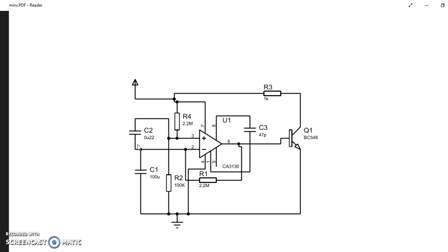An ordinary radio frequency detector using a tuned LC circuit is not suitable for detecting signals in the gigahertz frequency band used in mobile phones. The transmission frequency of a mobile phone ranges from 0.9 to 3 gigahertz with a wavelength of 3.3 to 10 centimeter. So a circuit detecting gigahertz signal is required for a mobile bug. Here the circuit uses a 0.22 microfarad capacitor to capture radio frequency signals from the mobile phone. The lead length of the capacitor is fixed as 18 mm with a spacing of 8 mm between the leads to get the desired frequency.